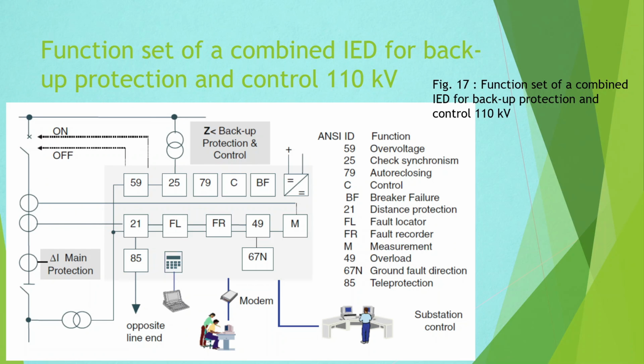The external influence generates an electric arc which shorts the affected phases. The fault disappears when the protection trip interrupts the energy feeding the arc. This means that the line can be switched on again. The reconnection is accomplished after the dead time so that the air can be deionized.